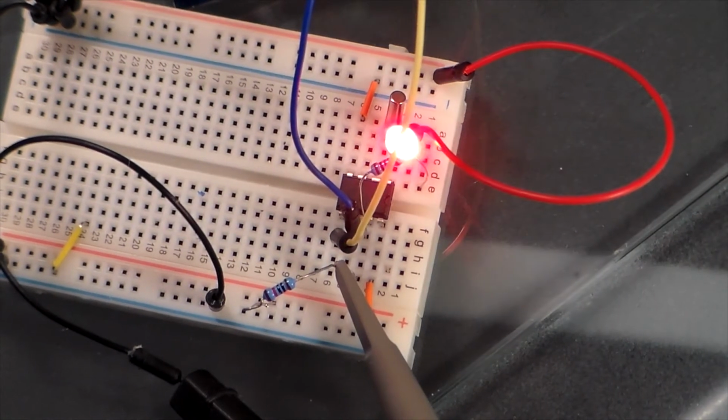Okay, so if you don't have an oscilloscope, you can hook up an LED to the output at 1 hertz because the light will flash on for 1/2 second, and then off for a second. So you can check to see if your circuit's wired up correctly, even if you don't have an oscilloscope for the 1 hertz. For the higher frequencies, you're not going to be able to see the flash. It's going to flash too fast, but you can see it at 1 hertz.